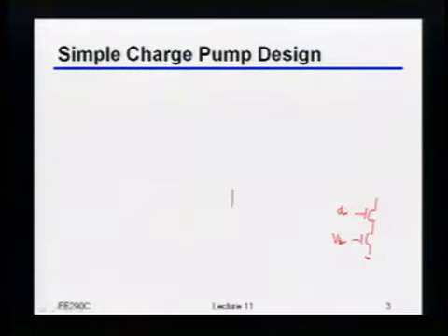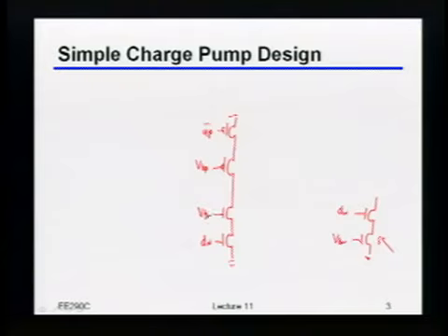The way the charge pump is typically done, I won't draw the full thing, I'll really just draw the output stage, but recall that you have to match everything up correctly. In the one that we drew last time, we put the switch on top of the device. Oftentimes you'll actually put the switch on the bottom of the device. As an example, this will be down, this will be up bar, this will be some bias voltage, and that'll also be some bias voltage. And then of course this would be your actual charge pump output.